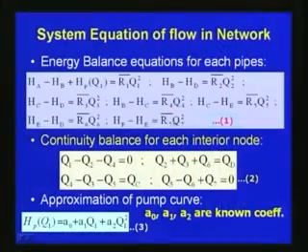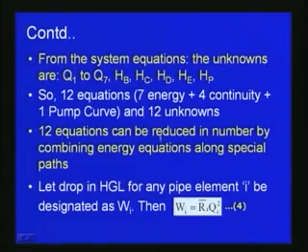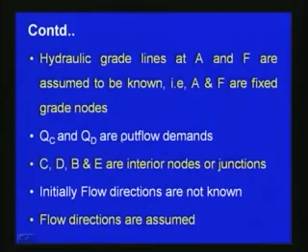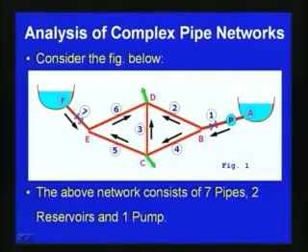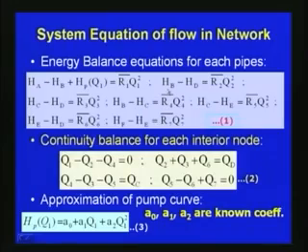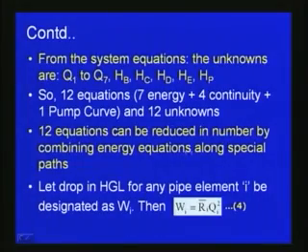Now, you can see that these equations are combined with respect to the discharge and heads. So we will try to reduce these equations in number by combining the energy equations along special paths. Different paths can be written like this or like this. Along different paths we will combine the energy equations such that we can reduce the number of equations and correspondingly the number of unknowns also.